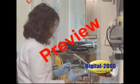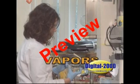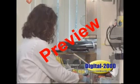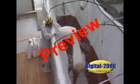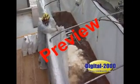The majority of occupational health hazards arise from inhaling chemical agents in the form of vapors, gases, dusts, fumes, and mists, or by skin contact with these materials. The degree of risk in handling a given substance depends on the magnitude and duration of exposure.